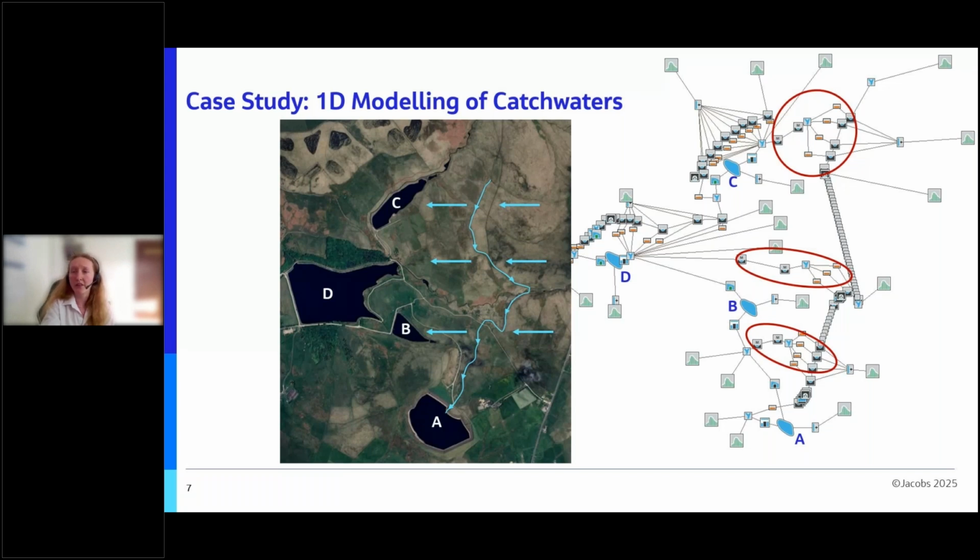And another reason why Muskingum units were chosen in place of, say, river cross sections is because the slopes were very steep and because we weren't particularly interested in water levels along these flow routes.